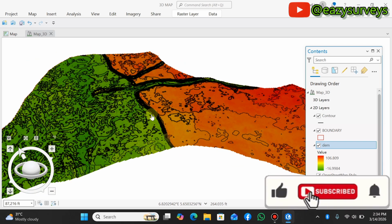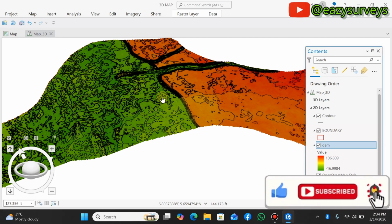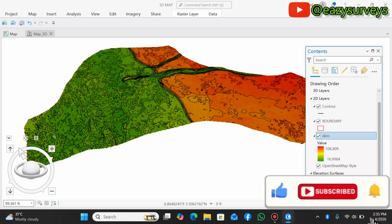So I made the color scheme to be different from the contour lines so that you can differentiate which data is which. Therefore, the next thing is to exaggerate the vertical elevations, because the vertical exaggeration is kind of low, so it's still not going to bring out the 3D view of your surface. So to work on the vertical exaggeration, you click on the ground, under your elevation surface, that is select on ground.